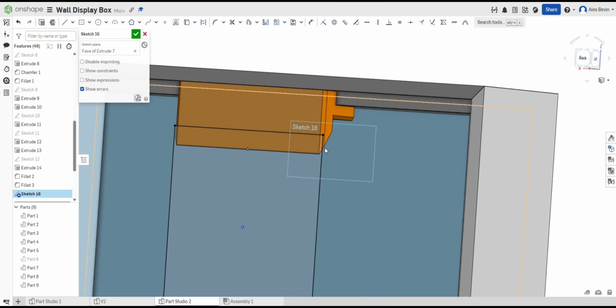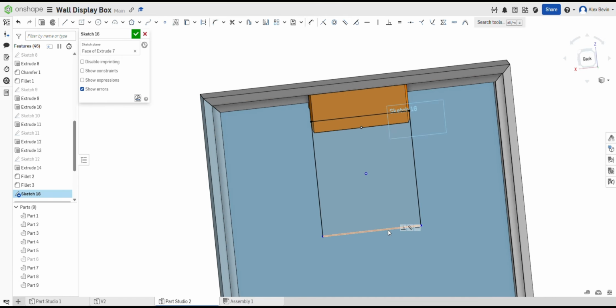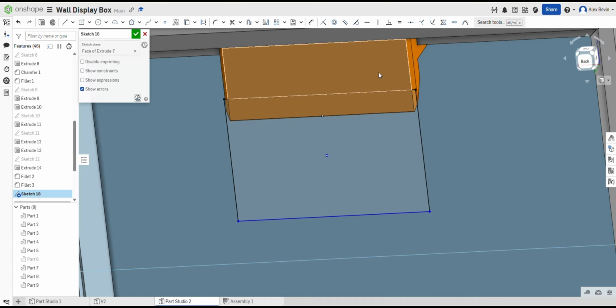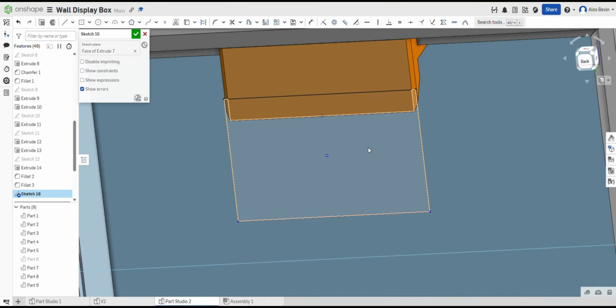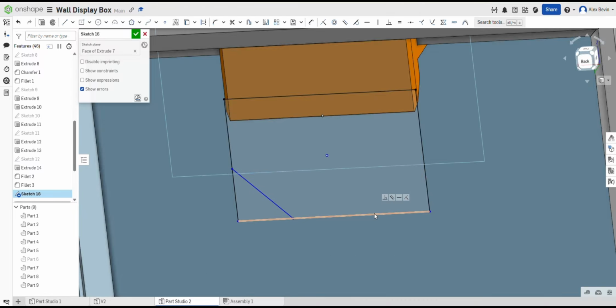Now watch this. These lines are dynamic. If I change the top width later, say to 150, this updates too. That's what we want. Next, we're building the chamfers into the sketch. Press L for line. Now press D for dimension. The bottom flat of the chamfer is 10 millimeters, and we do the same on the other side, 10 millimeters.